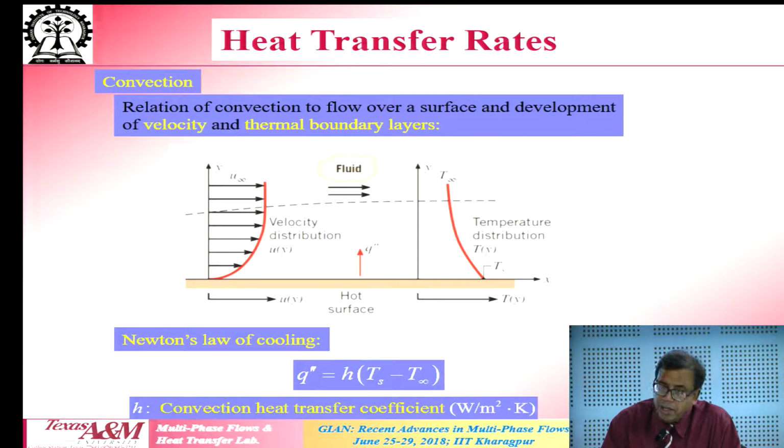Now when we teach this particular equation, this is valid for a macroscopic system. When we get to nanoscale heat transfer, particularly the interface between a solid and a liquid, we will see that this can actually get violated, because sometimes you do end up with a thermal diode on the surface, as I mentioned earlier. When you have a thermal diode, Newton's law of cooling needs to be modified, because in this particular case whether you have a hot surface or a cold surface, it does not matter, as long as your temperature drop is the same, your heat flux will be the same. But that particular modality may not always be valid. So, we will revisit this equation a little later.